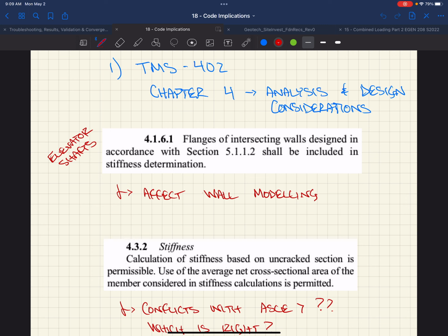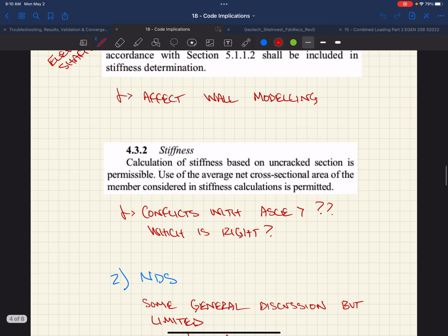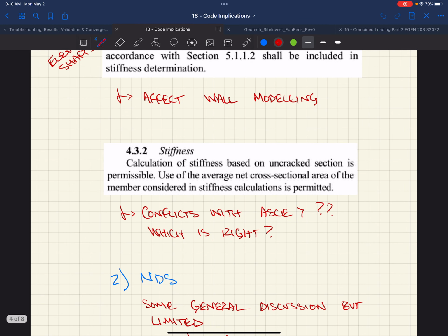There were some existing masonry walls in the health center that were shear wall elements, okay? And you have to incorporate the fact that you get some composite action when you have these walls intersecting at corners. Stiffness, right?